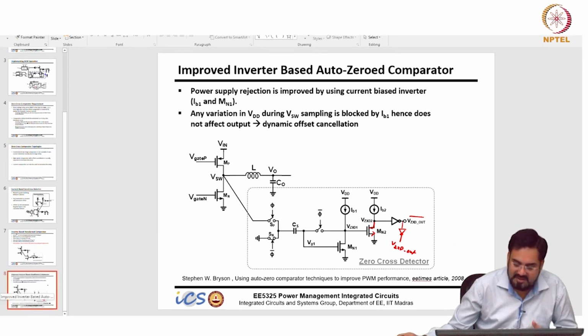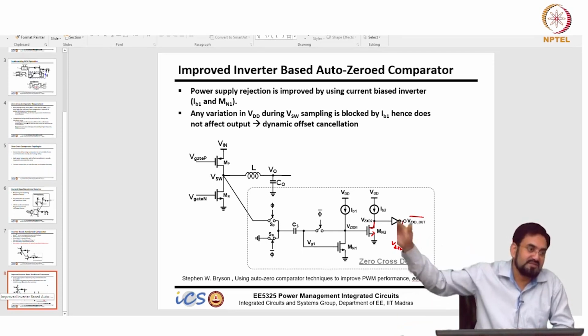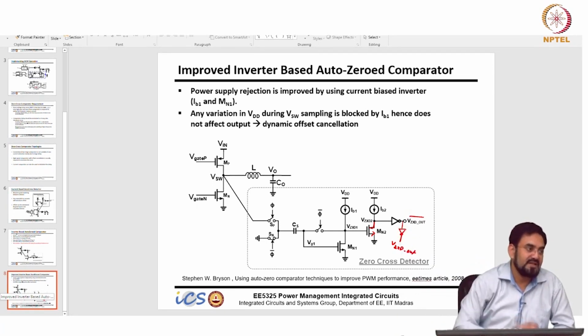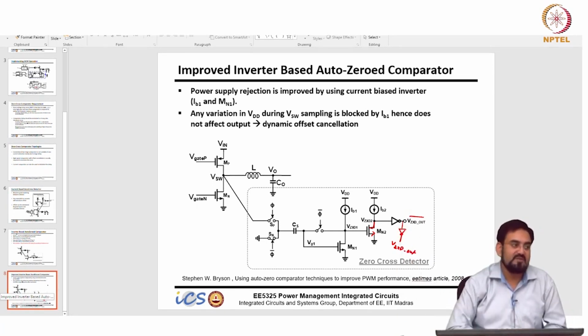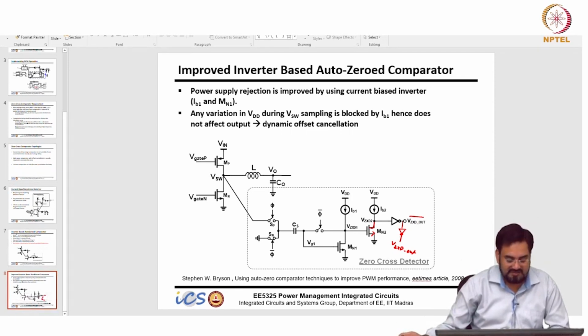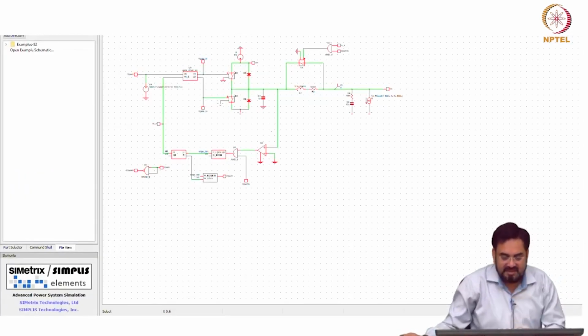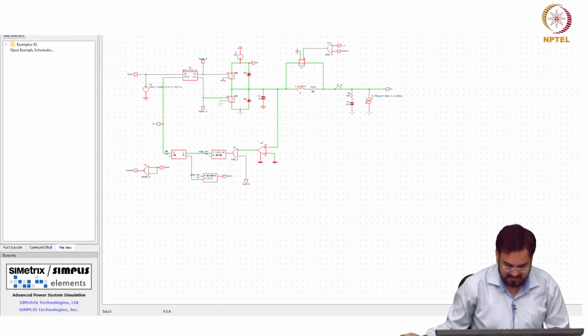Because it's quite possible that when you hit the D min, your load would have dropped to very low current and your switching losses may start dominating. So, in that case you want to enter the PFM mode a bit early and start reducing the switching frequency to improve the efficiency. So, this is a simple implementation I have to show you.